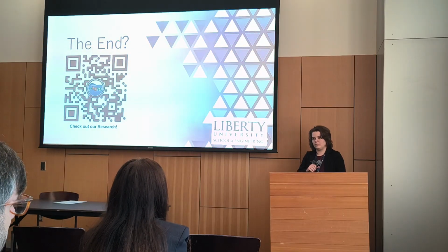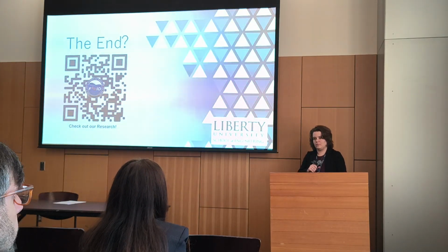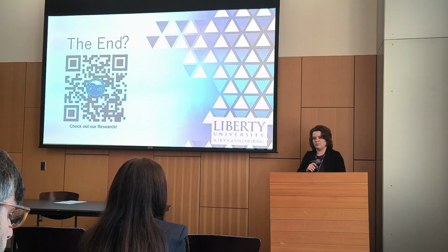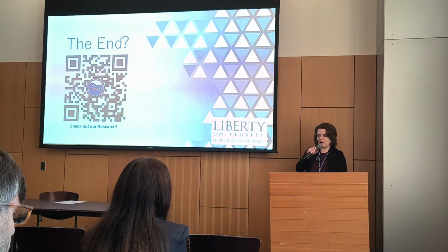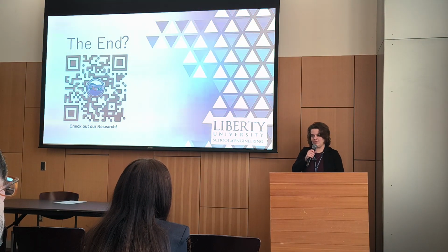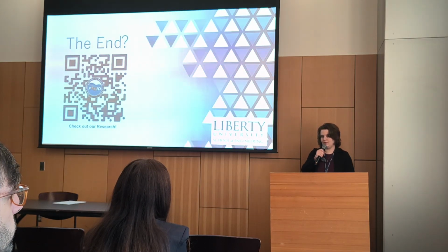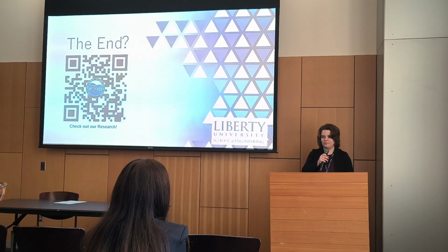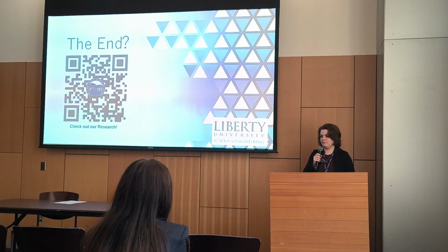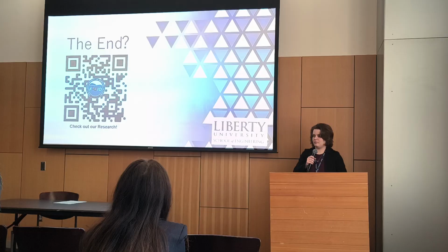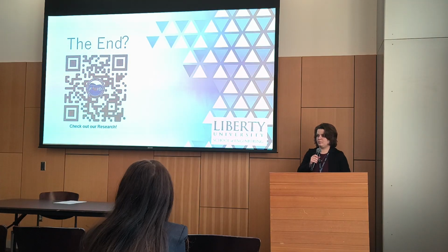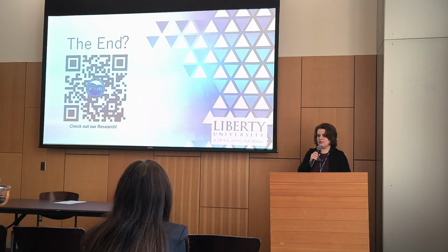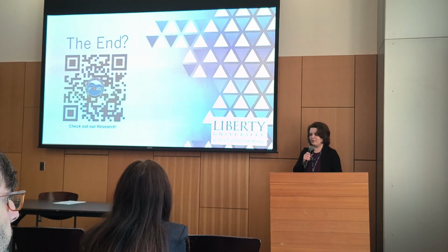Do you know the error constructed using the experimental results? I mentioned it a little bit while I was talking about U-naught, but they said they had a 10% error when they were measuring with their data. So was the LES done on the same 2D mesh, or was it a three-dimensional mesh that you created for the LES? It was a three-dimensional mesh used for everything.